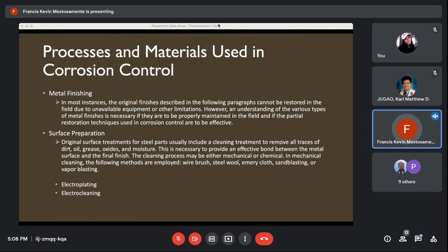So how is the process done? With electroplating, same yan with the redox process. So we got an anode and a cathode. So binalik natin yung process ni corrosion sa kanya and we use this process to defend against corrosion. So pili lang to, yung electroplating. So may mga piling material lang where we could process the electroplating. Kaya common lang is gold. We got common materials. For example, we got brass to copper, steel to chrome, copper to gold, and several other materials.